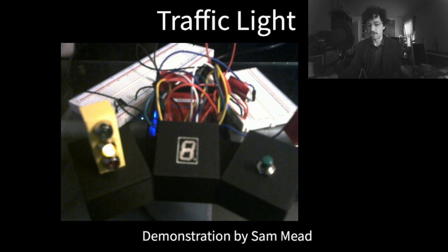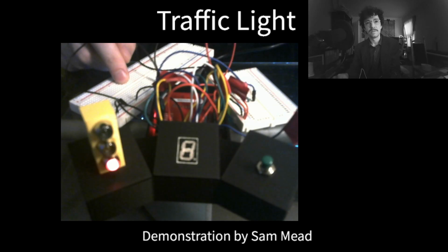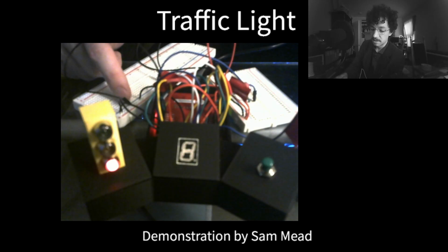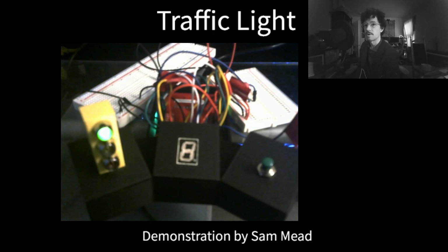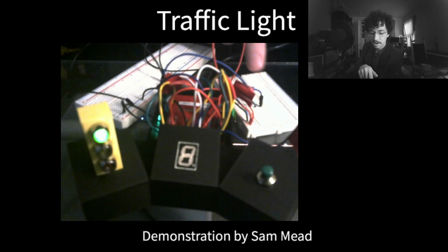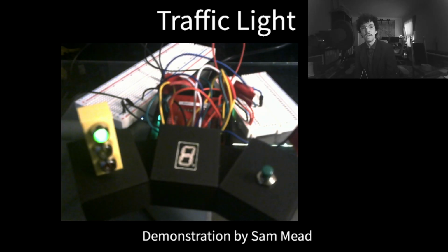And as far as physical connections go, I do have 2 breadboards here, really just a convenience factor. One of them is for expanding the amount of ground nodes I can have. So essentially we have this ground node here that connects to all of the ground connections for the LEDs because they are positive logic, and for the switch, which is also positive. On the other breadboard, we have our 3.3 volt connections for expansion and the resistor for the switch, the pull-down resistor. So that is about it.